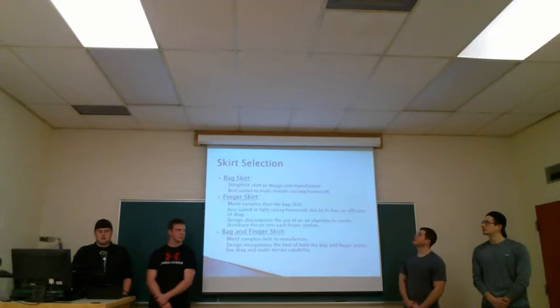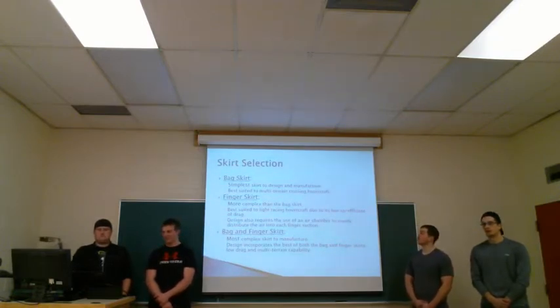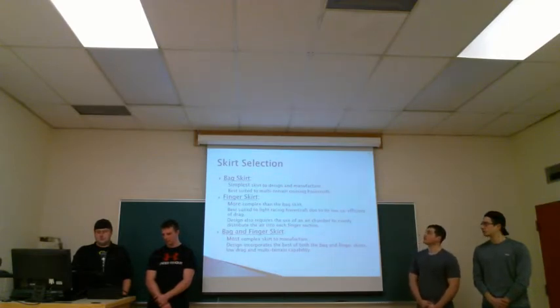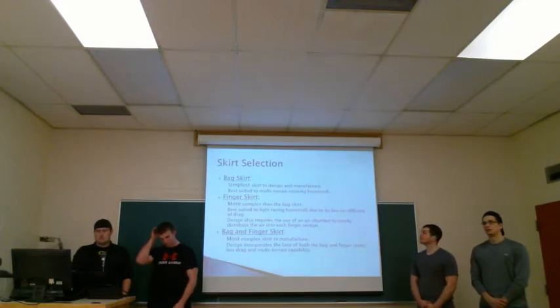And another section of the hovercraft that we had to choose for is our skirt. So we had 3 choices. We had a bag skirt, a finger skirt, and a combination of both. So the bag skirt is the simplest design, both design and manufacture, and it's the best suited for multi-terrain.